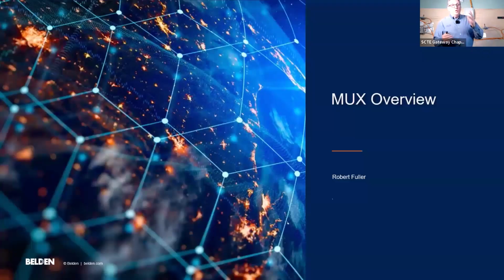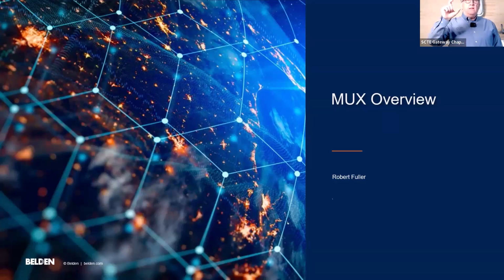All right. So that's pretty much it for fiber basics. Remember, as we're going to the house, keep them clean, wear your protective gear, treat fiber like it's alive, and watch out for your bend radiuses. One last comment on the bend radiuses. I've been lucky enough to go out on some visits with the techs that are installing them. There are clips designed by the fiber manufacturers to hold their fiber. I know a lot of guys are still using E-clips and Roker style clips to hold them in place. Just be careful. Remember the little micro bend we're talking about with the fiber.